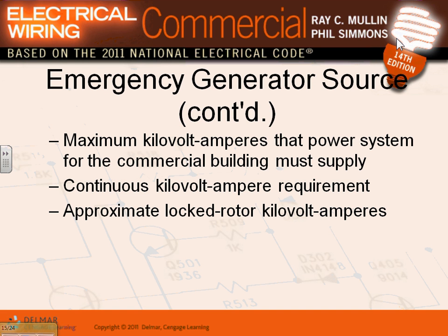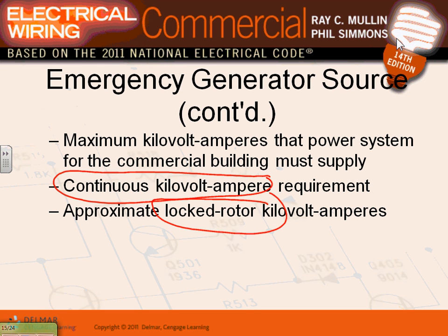A commercial building must supply continuous KVA and locked rotor KVA. So when we size again, I can't emphasize enough the continuous KVA, that's my running, and the locked rotor KVA, especially for motors, especially for machines. Because to start a machine, guys, is not like starting a lighting fixture. The starting current on a motor is 6 to 10 times more than the starting current on lights and so forth.